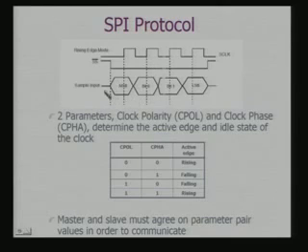And this is a sample input. So, you have got again the same condition that you start with MSB first, just like in I2C I had the most significant bit sent first, here also the most significant bit is sent first, and the entire sampling or the data valid time is defined with respect to the rising edge of the clock.